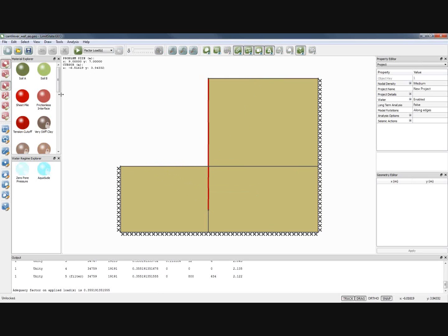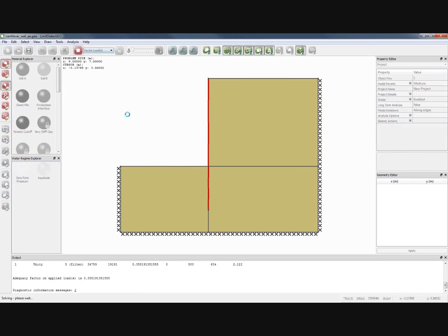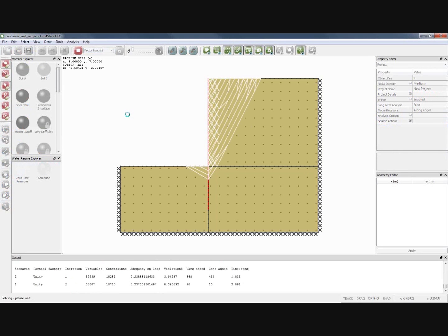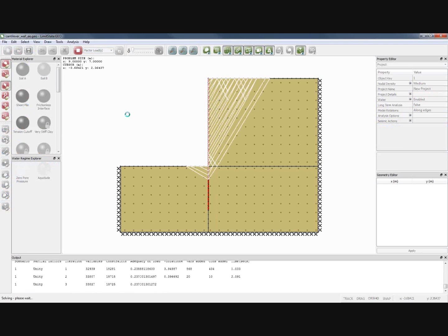But if you want to look at plastic failure of the wall, we can reduce that. So if I reduce that plastic moment of resistance to, say, 15, which is below that 25 that the analysis told us, then the software will find a different mechanism of failure where in fact the wall is going to fail by bending, and we get a sort of shallower failure.